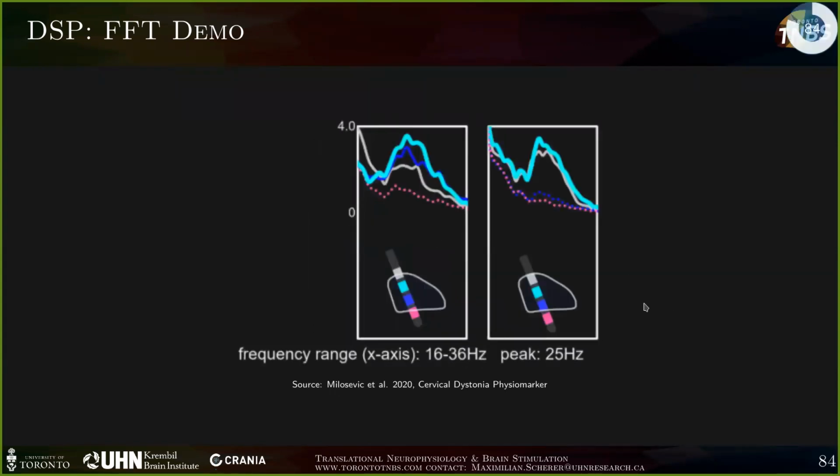And the same applies here. If we take a look here, we see that the frequency peaks at 25 hertz. That allows us to make the conclusion that at, let's say, 20 to 30 hertz, if we take the sinusoids within that frequency range, they represent a significant chunk of the power that we just observed.